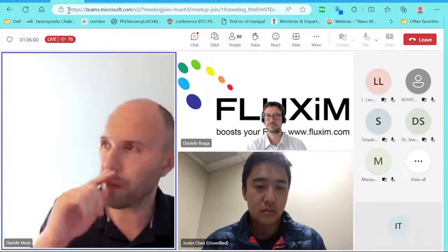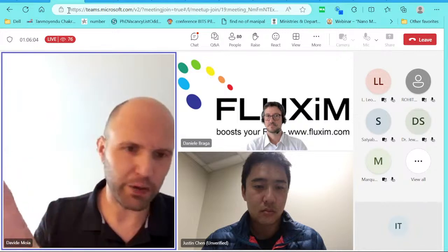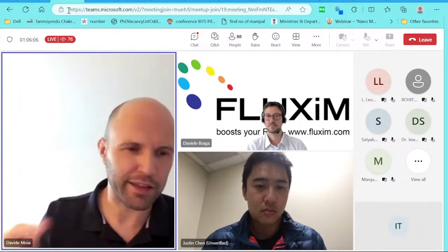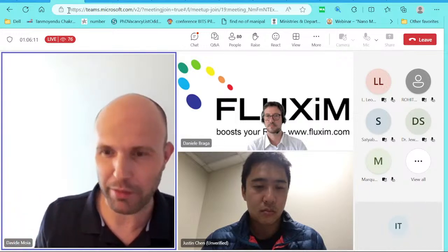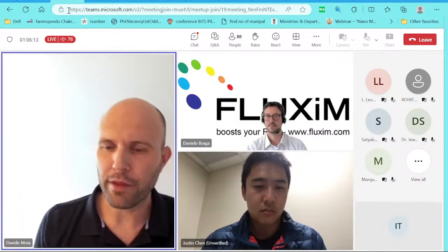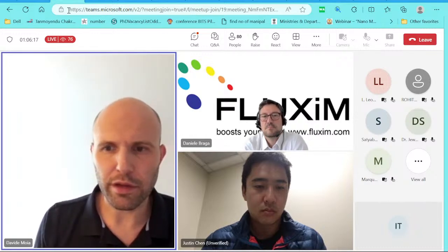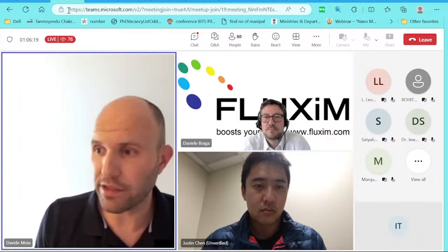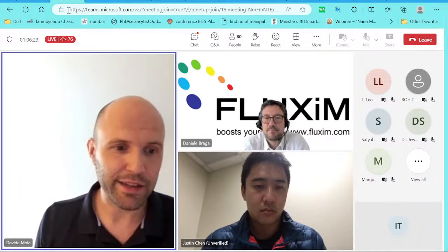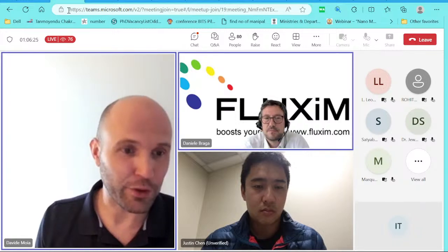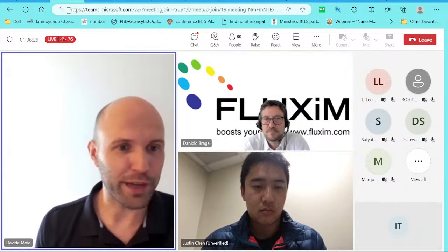And for the one with the single transistor, I did the fitting manually because getting a fitting procedure to converge was a bit tricky. It's probably something that can be improved. One of the issues in these situations is that you potentially have a lot of parameters, and you might not have a single solution to your fit, or it will depend on how you define your minimum.